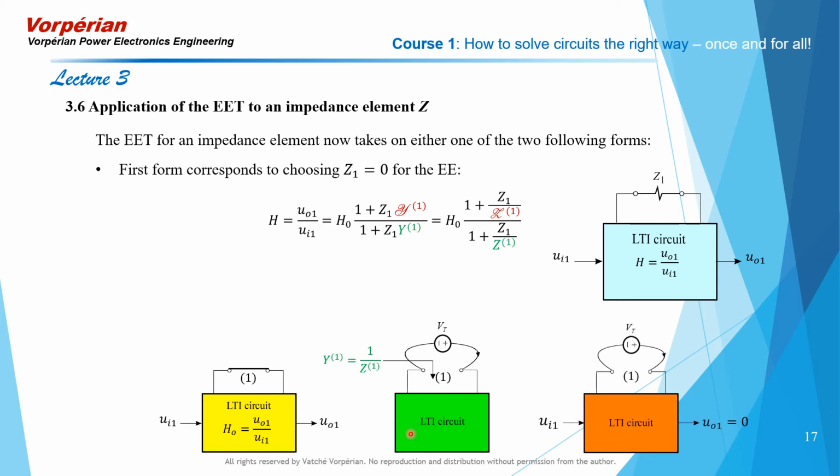And last, what we did was we computed the null input admittance looking into port 1, but this time with the response nulled. And we accomplished that with the applied voltage source, or you could have easily used the current source if you wanted to, it didn't matter, with a voltage source connected there and the original excitation in the circuit of the transfer function.